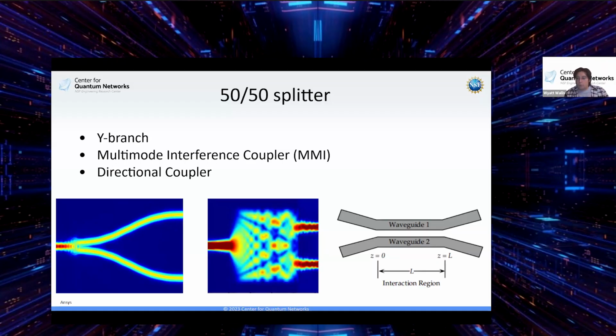Now, sometimes those go off a significant amount, and if you bring another waveguide very close to your first waveguide, that tail can couple into the second waveguide, and essentially power can be leached off of the first.